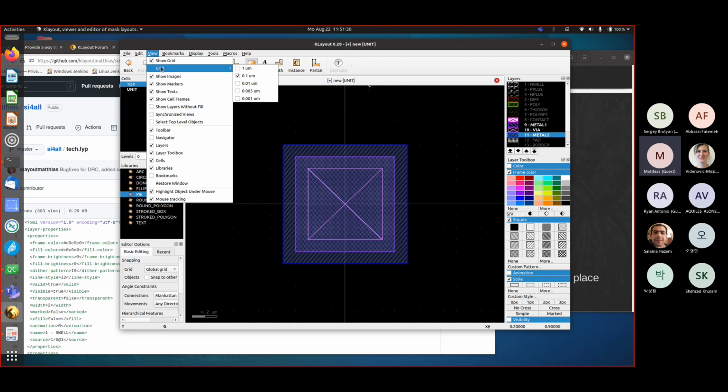You can go to File Setup, and there's grid. Sorry, default grids. And then you can add some more, like 1, comma 2, 1, or something like that. And then you should see the others, and you can choose coarse. Okay, great. Thanks. Yeah, it's much more convenient to work with coarse grids.